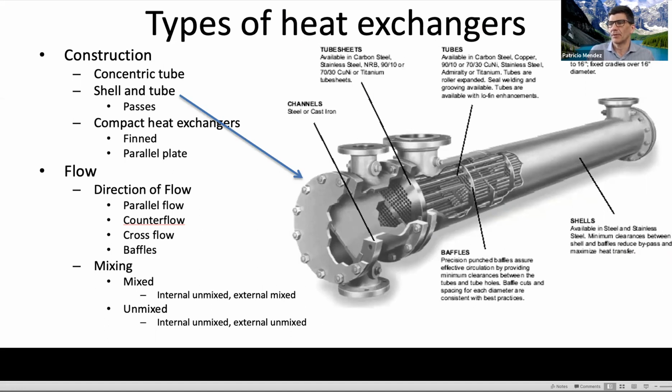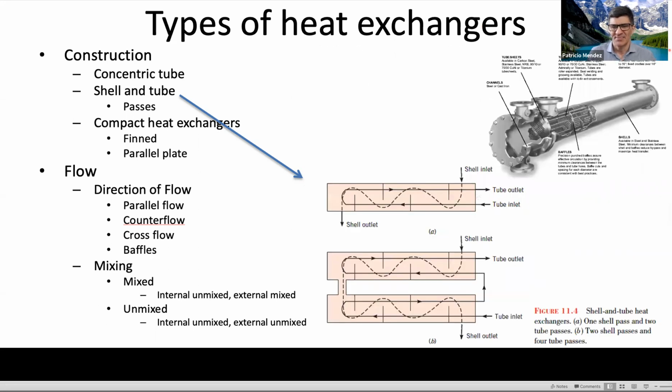We saw the different types of heat exchangers like shell and tube, whether we have one shell and two passes or two shell and four passes, or some multiple of four passes, that eventually these configurations not only have implications from the point of view of cost and footprint on the plant, but also from the point of view of the calculations, there are particular correction factors associated with this.